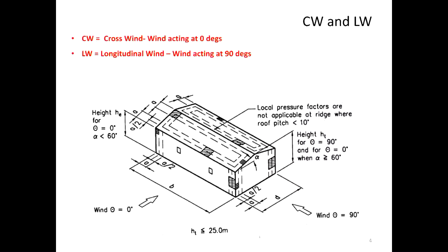So I think I explained this yesterday: when you have an industrial structure, usually it's a rectangular shape, usually about a 1:3 or 1:4 ratio, where that might be 50 meters and this might be 200 meters. Along the longer direction, I explained that side of the facade or the cladding will attract more wind because it's got a much larger area. Is that correct? Remember that yesterday?